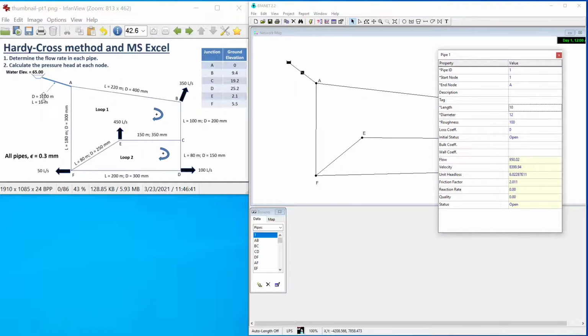Here I've written diameter as 1,000. I meant millimeters. The point is, I want it to be a really big pipe so that there isn't any loss through that pipe. So 1,000 millimeters, and the roughness is 0.3. I don't know if it matters either way, but okay, so now I've put the characteristics of that pipe in and execute the model. This time it's successful without any warnings.